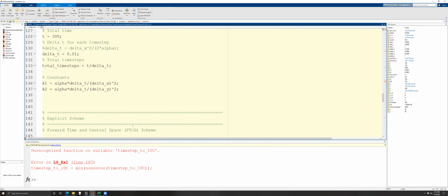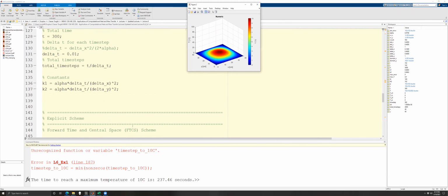So I think for us to play around with that, the time step size was fixed to define the upper bound. But I encourage you, if you go through this process, see what happens if you do exceed that criteria, where your delta t is too large, because you're going to visibly see some really funny results come out.